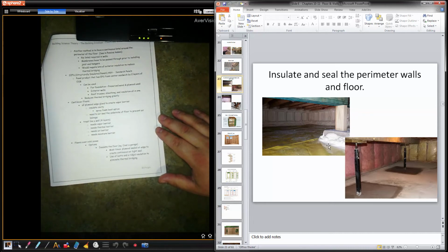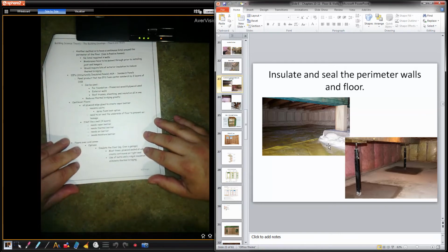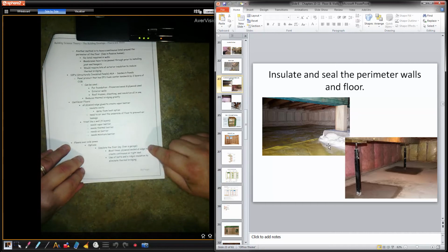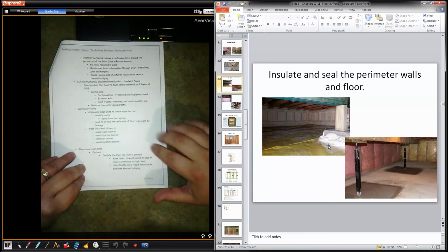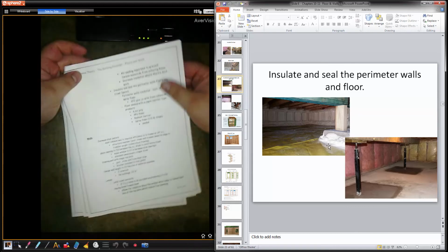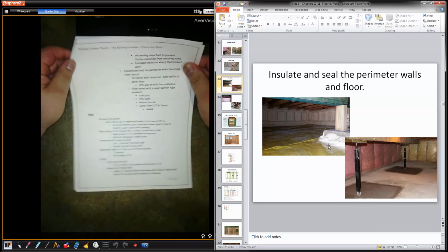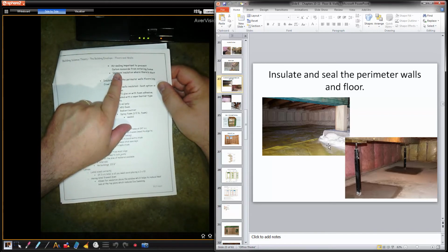Floors over cold zones, we kind of looked at that. Most times plywood sealed at the edges creates a continuous airtight seal. Also, vapor and air barriers could use batts and rigid insulation to eliminate thermal bridging. Kind of look at that over the garage. Air sealing is important to prevent carbon monoxide from entering the home. So making sure it's well air sealed.